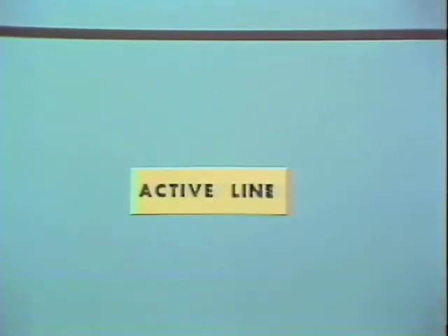We'll now look at this pattern of horizontal lines in more detail. The dot or beam starts scanning the picture at the top left-hand corner of the screen. It travels across the screen to the right-hand side. This left-to-right travel carries and displays the picture information, and it is called an active line or scan.